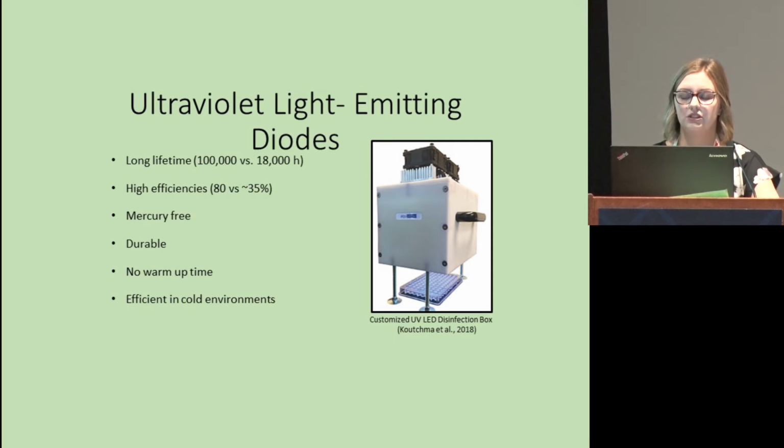Ultraviolet light has been used for many years in different industries to inactivate microorganisms, including for water purification and pharmacological purposes. It has a relatively low penetration rate, so it is ideal for flat surfaces, air, and transparent liquids. On the electromagnetic spectrum, we have UVA, which is from 320 to 400 nanometers, UVB, which is from 280 to 320 nanometers, and UVC, which is from 200 to 280 nanometers.